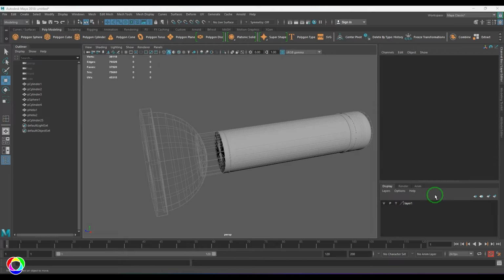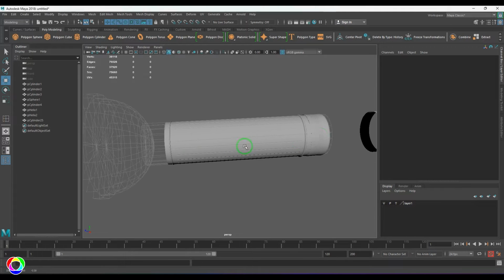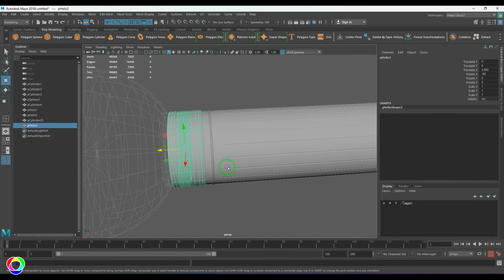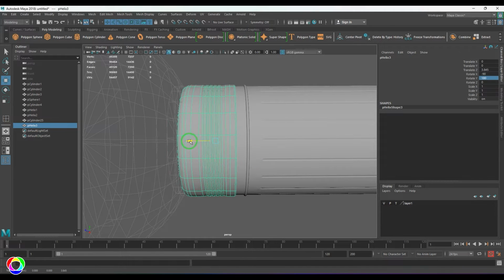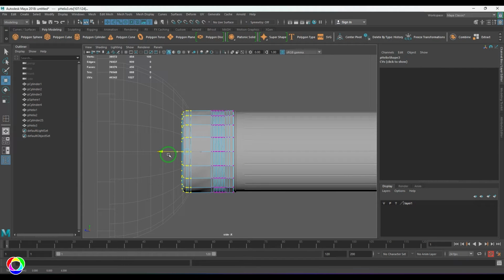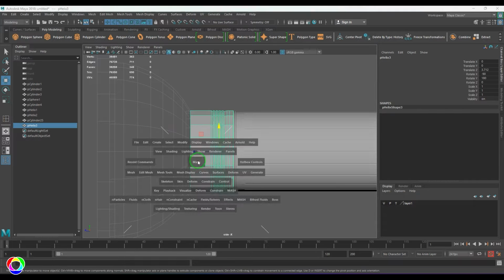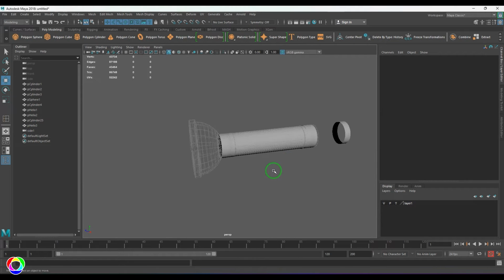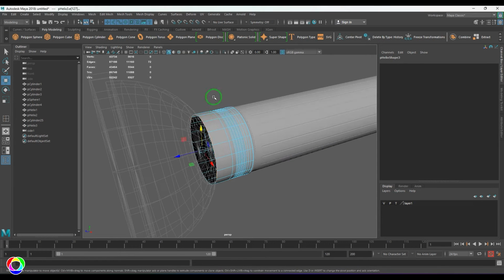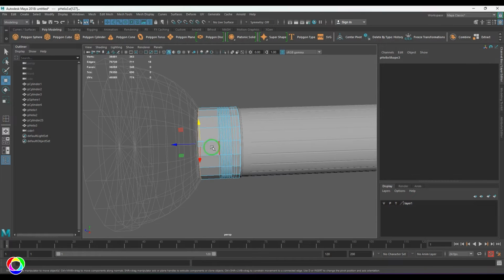So I need to put up this detail what we have got here on this side also. So I'll move it up here, rotate Y 180 degrees so that comes on this side here, and I'm going to move these vertex points up to this, and I'm going to delete that. Okay, so you should be able to get that nice cap on this side as well. That looks good. Let me select the line. You have 18 points here, and the reason I'm looking for this is I want a very similar number of points on this side too.